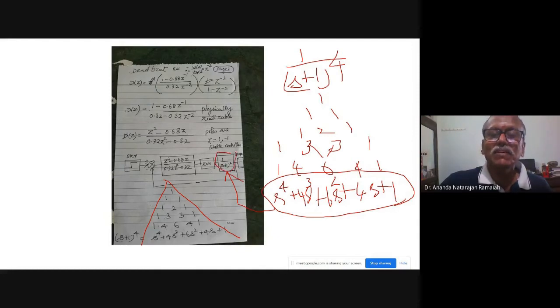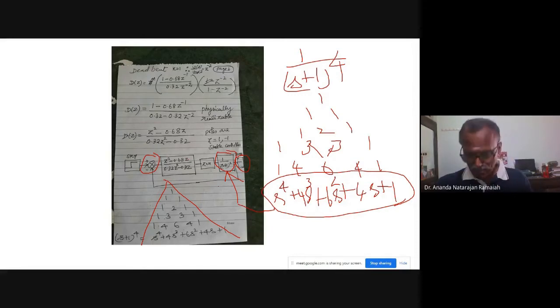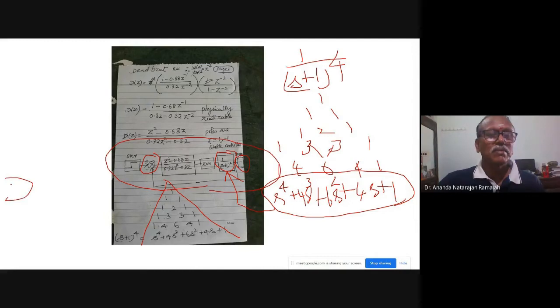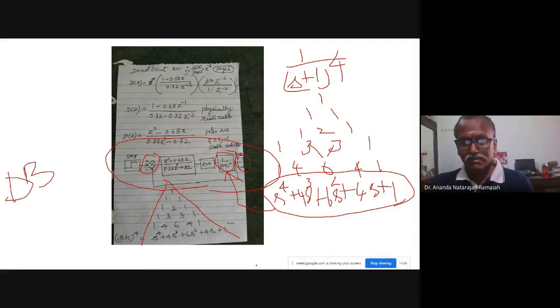This is a continuous transfer function. Then put a scope from the sink module. You can get the scope. Then take a summing junction. Then connect all these things as shown in the figure. Then you will get the deadbeat controller. This is the deadbeat controller. Now let us simulate the deadbeat controller.